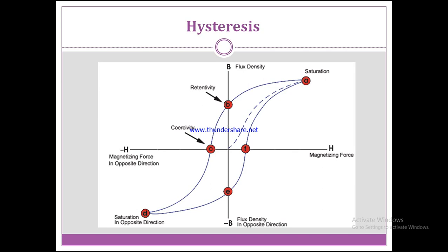In fact, the coercive force comes into existence due to all these imperfections, because of the energy required to move a domain over an imperfection. So, if a material has large internal stresses and non-magnetic inclusions, then the coercive force will be large.